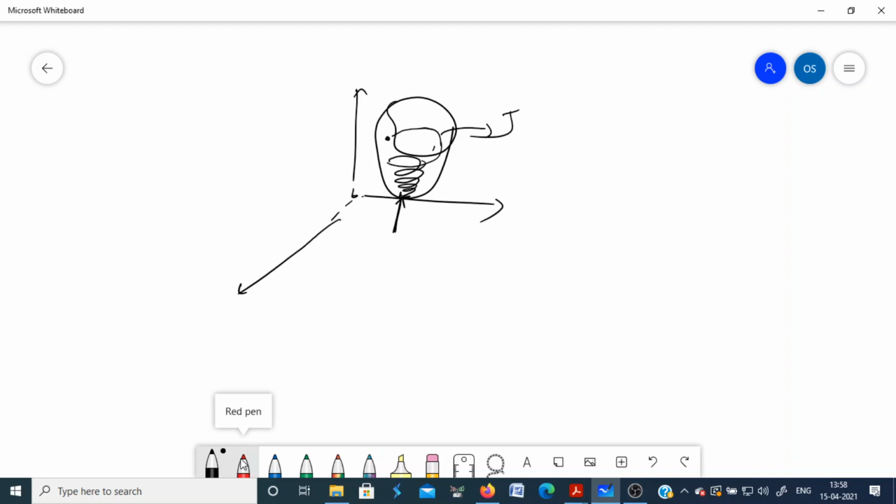In adaptive beamforming, adaptive filters or Wiener filters are also used, in space division multiplexing. You have an array of antennas, and if you want to focus the main lobe in a particular direction, that can be done using adaptive filters.